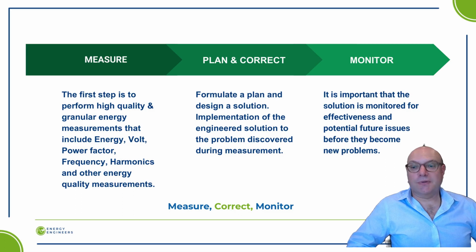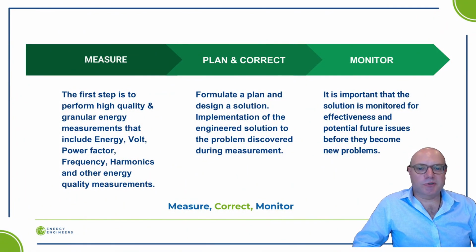The next step is monitoring energy demand and power factor. After the changes have been implemented, it is important to test that the changes are sufficient and that they stay sufficient over time. We generally advise permanent energy measurements and monitoring of most installations, to prevent problems in the future and to find issues with machines before they cause machine breakdowns.